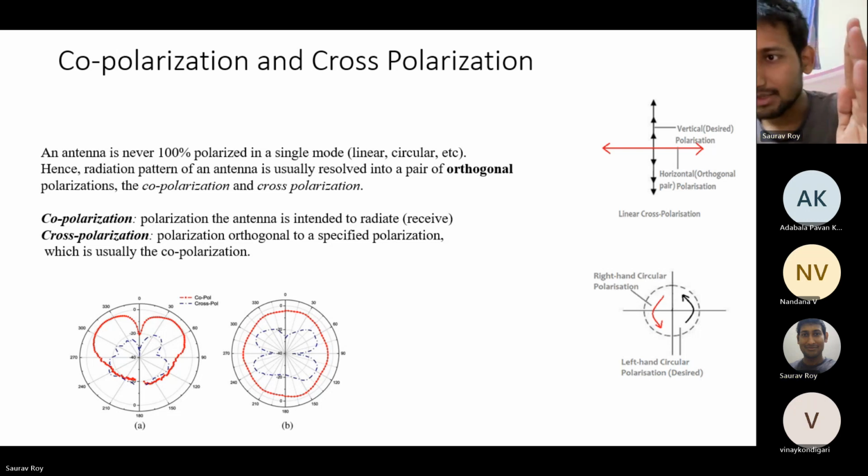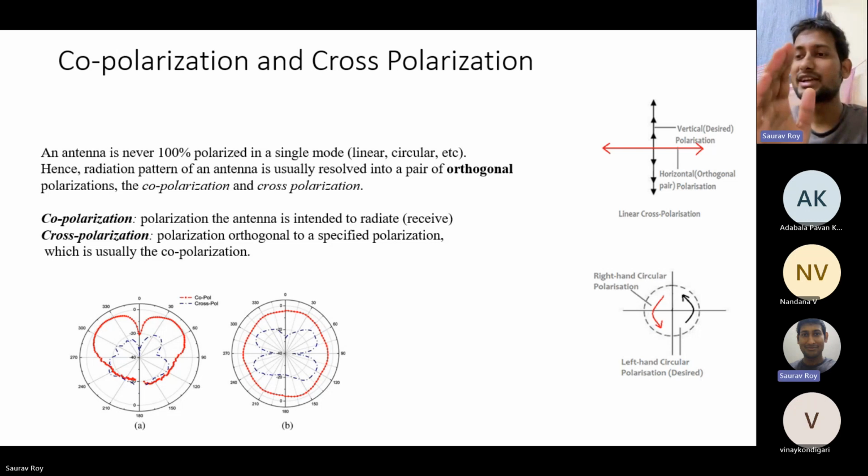Now let's say you have fabricated another antenna, and you have to measure the radiation pattern, polarization, gain and directivity. This reference transmitting antenna is fixed, and the fabricated antenna, my right hand here, we connect to the receiver. Both of them are kept like that.